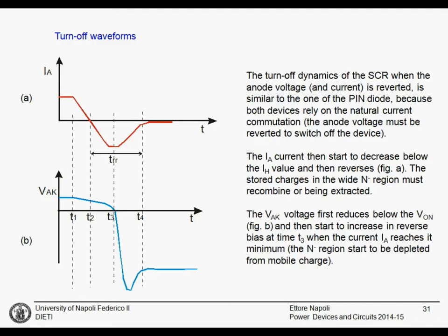But there will be also a large base current coming from these very wide, very far away places of the thyristor. And this large base current will cause a voltage drop on this layer. This voltage drop at a certain point of the device will be large enough to switch off the device. And this means that these regions far away from the gate will stay on and will be on even if there is a negative gate current.